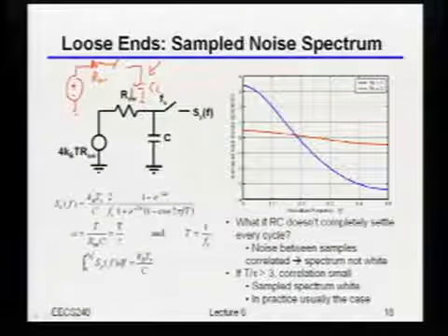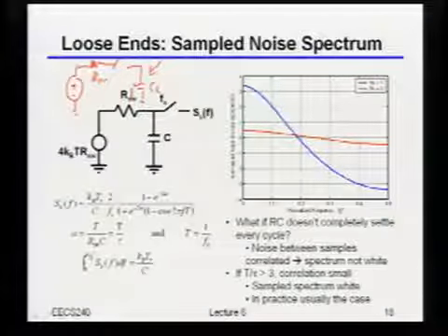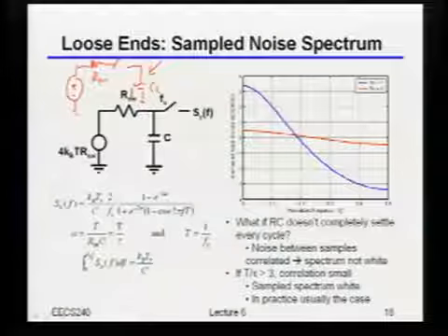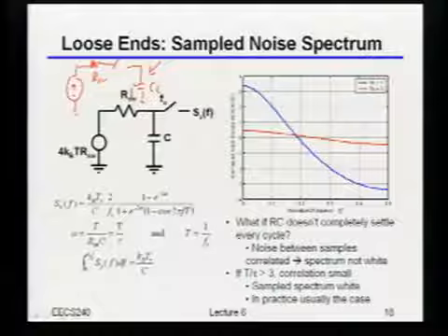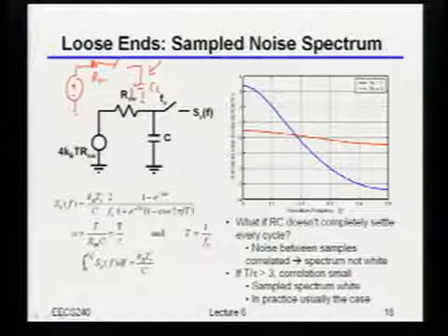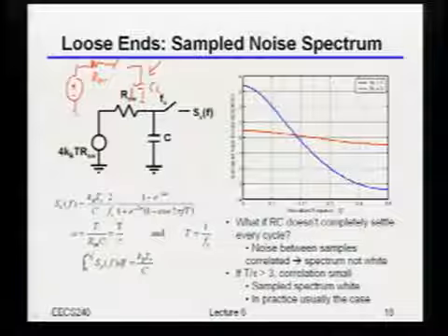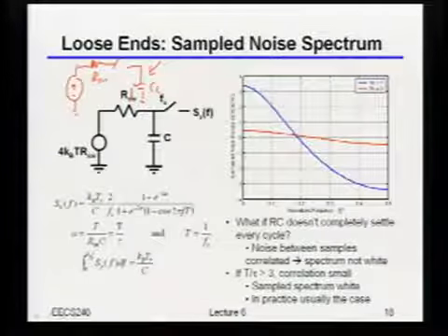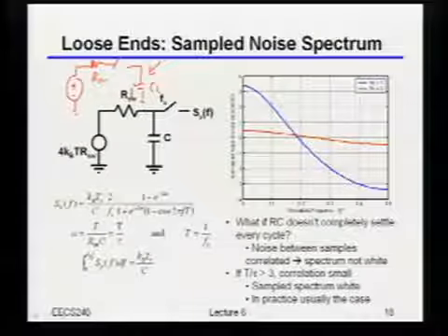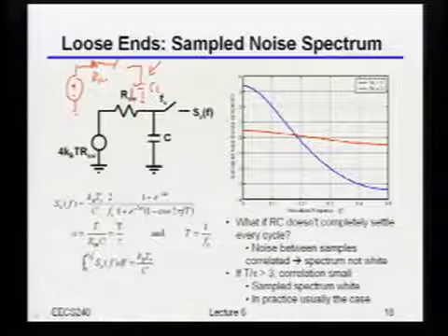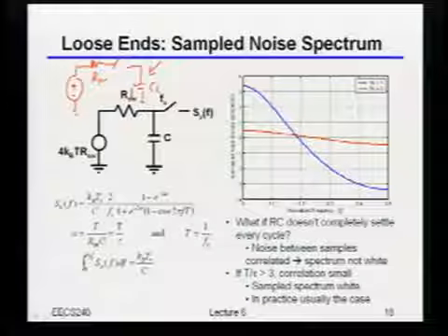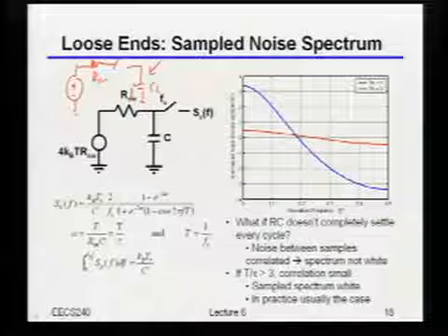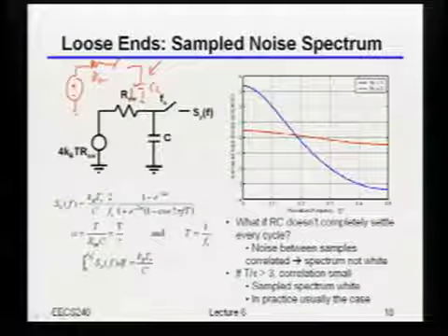But in practice, let's say you wanted to build an oscilloscope or an analog to digital converter or something like that. You don't usually want a sample of the input at just one point in time. You actually want it at many points in time, usually at a repetitive time spacing, right? So as an example, if you bought a scope, it might have a 20 gigasample per second A to D converter in there, or even a 40 gigasample per second A to D converter, meaning it's taking samples every roughly 50 picoseconds or so, right?